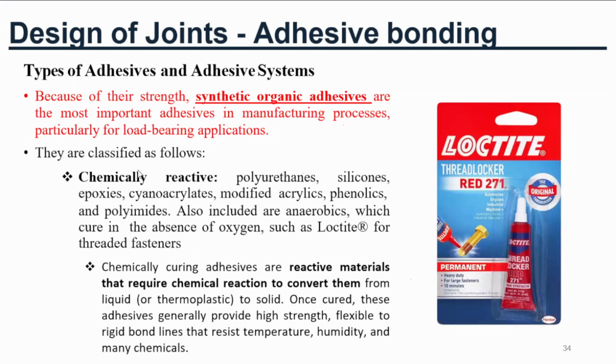These adhesives are the most important in manufacturing, okay, especially load bearing or structural applications. So importance is they provide high strength and durable bonds. Okay, commonly used in engineering and industrial assembly processes, used where traditional fasteners, bolts, rivets, welding, okay, these are not suitable.